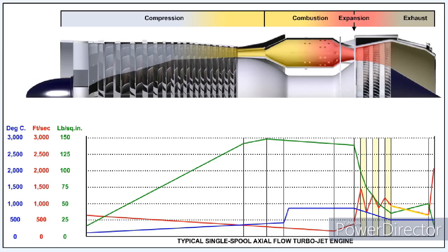As well as helping to reduce the velocity of the gases leaving the turbine before they pass down the length of the jet pipe, so minimizing turbulence, the exhaust cone also prevents the hot gases flowing across the rear disc face of the turbine, further reducing disturbance and preventing overheating of the disc.